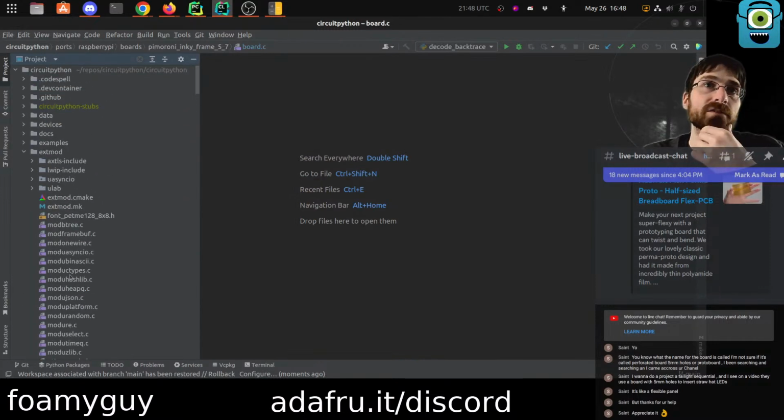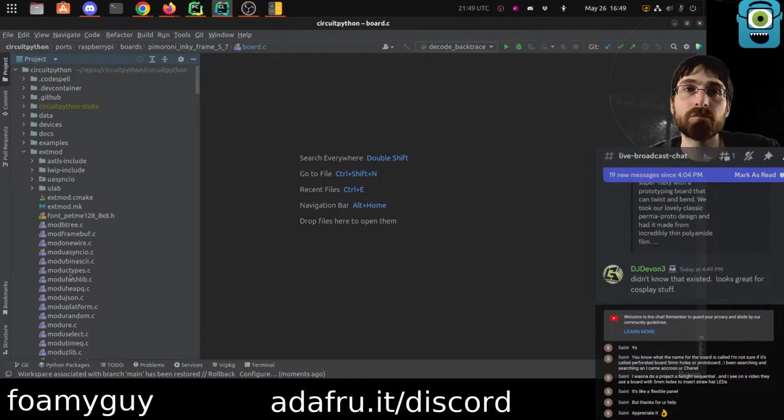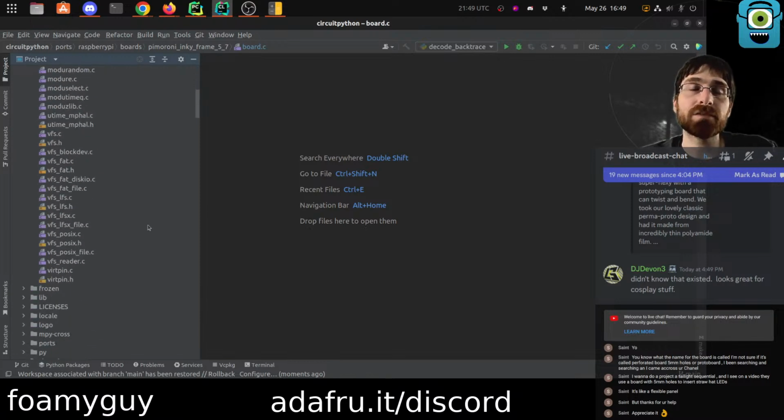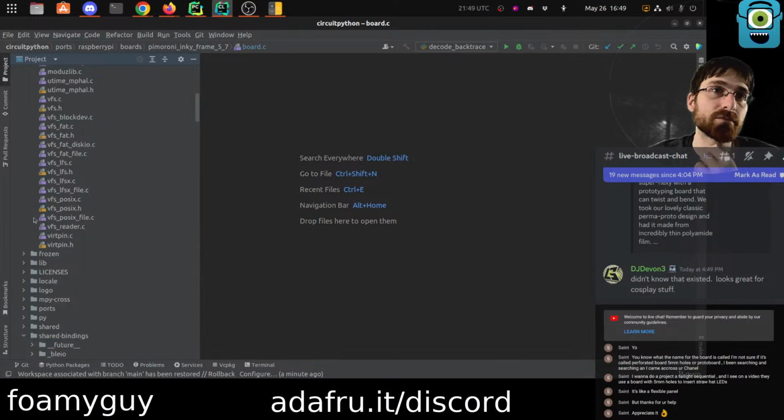But it turned out that I don't want the SD card initialized inside the core because I want to be able to initialize it, read the file off of it, update the display, and then unmount it, so that way if we reset or if anything else happens, we don't have it initialized. That way we won't get corrupt files and stuff. Whereas if it's initialized inside the core, then it's always initialized and mounted. If anything goes wrong, it could be halfway through writing a file or something like that, which we wouldn't want.